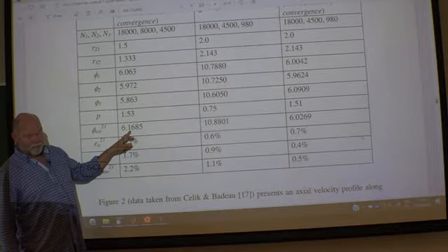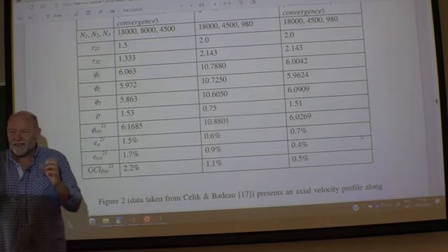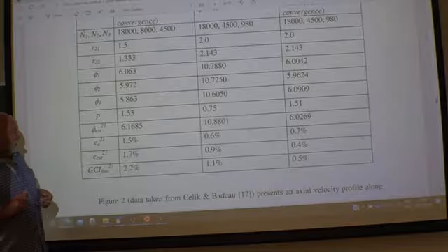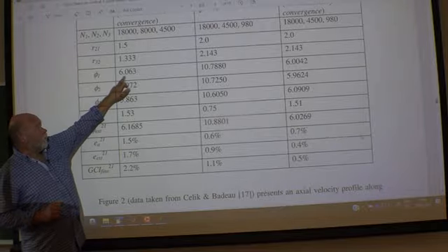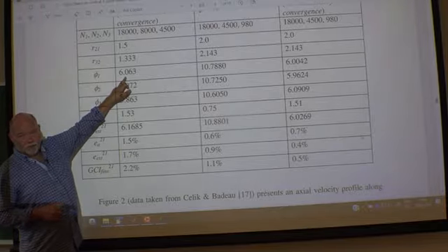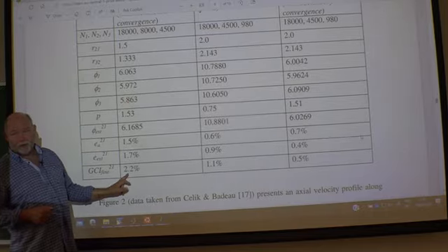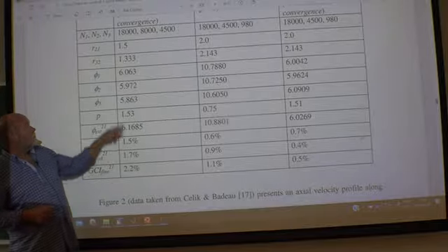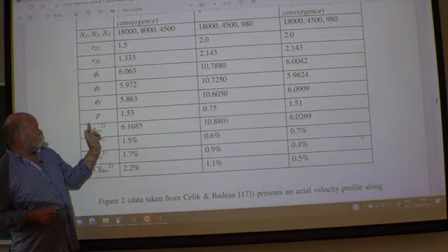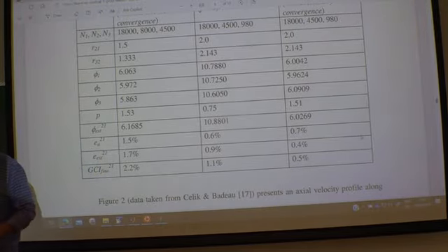But it's tempting. Maybe this one is a very good result, so be it. You can report it, but then of course you have to say, this is the extrapolated value. What instead you should do, you take your finest mesh solution and you say, this is my answer, plus minus 2.2%. That is the way you should do it. So use the fine mesh solution, not the extrapolated one. A little bit dangerous, to say the very, very least.